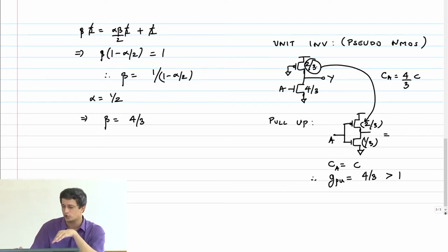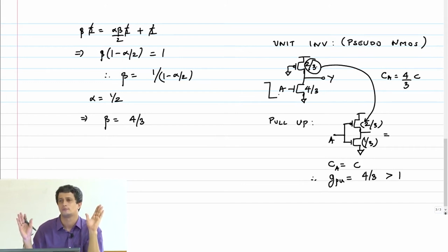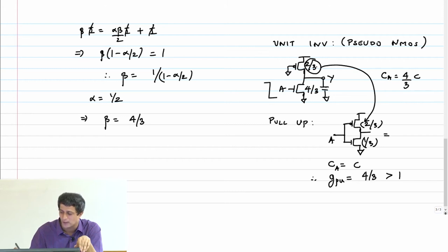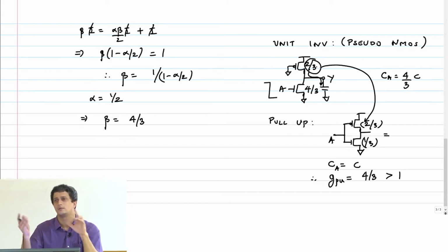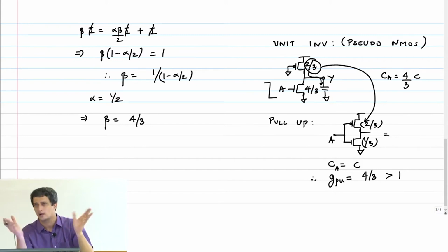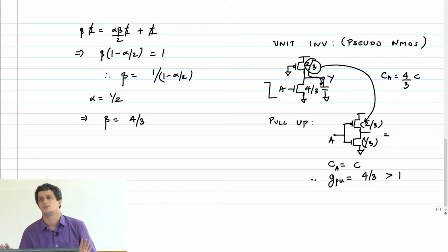So here there is no confusion because when the output is being pulled up, it means my input fell instantaneously and therefore the NMOS turned off. So all the current that is coming from the supply is flowing through like this. And therefore I said I can interchangeably talk about resistance and current here because the same current is flowing through the load capacitor, no problem. So therefore that 2/3 I replicated here, constructed the NMOS size and got the logical effort as 4/3.